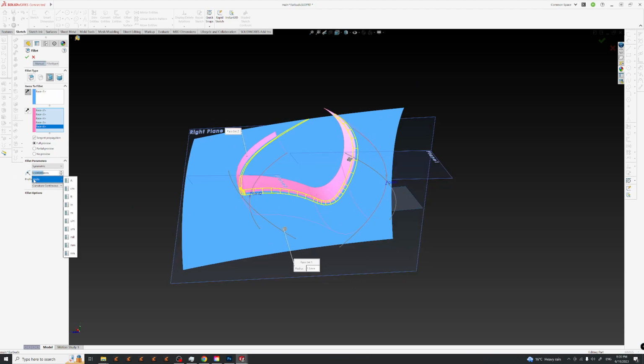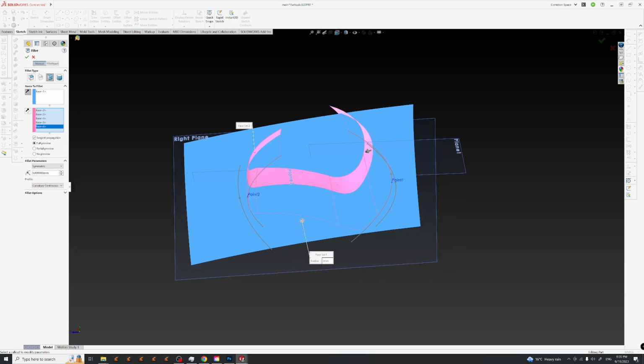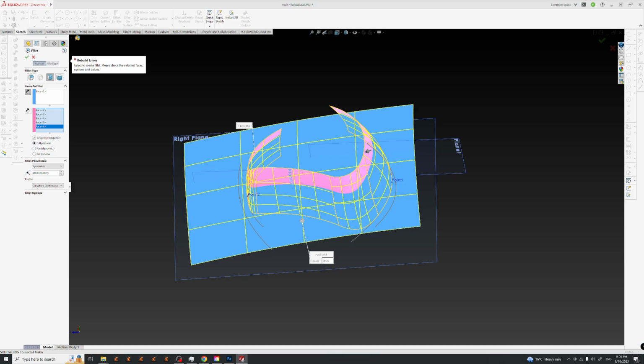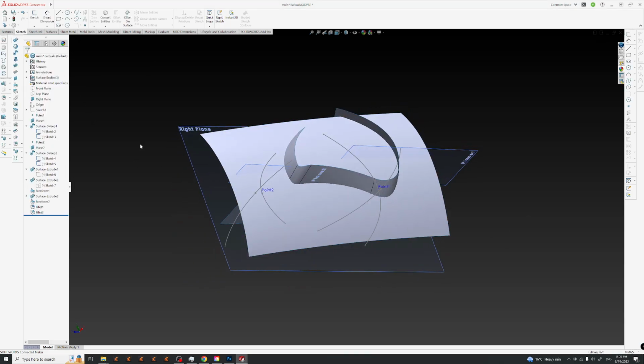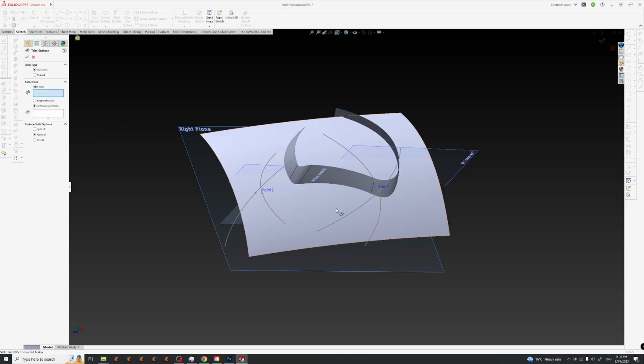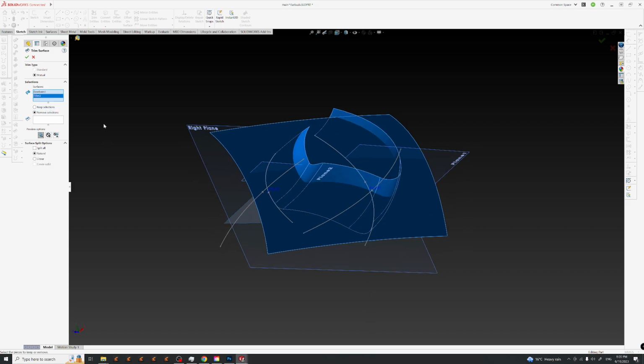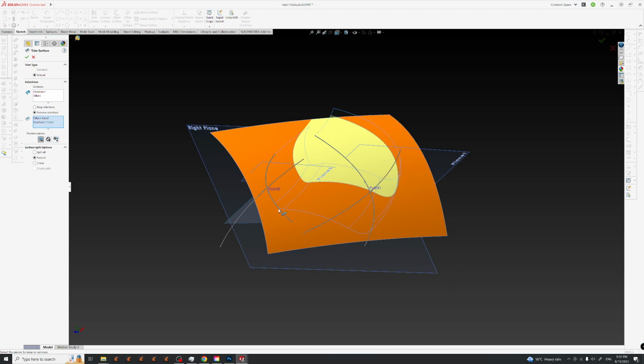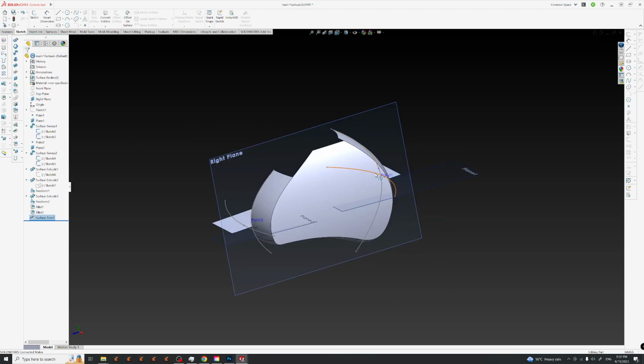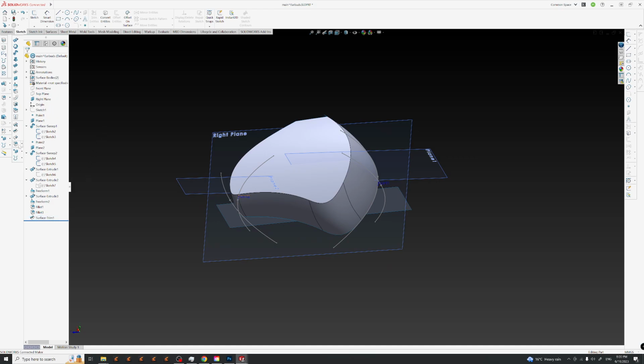Okay, let's try again, 3. Nah. So most probably we will have to do it manually. But, let's try another one. Instead of that, let's trim it. So I select trim mutual so that I gain some time. So between these two surfaces, and now let's remove selections. So I want to remove this and I want to remove that. Okay, and now let's try the edge fillet instead.